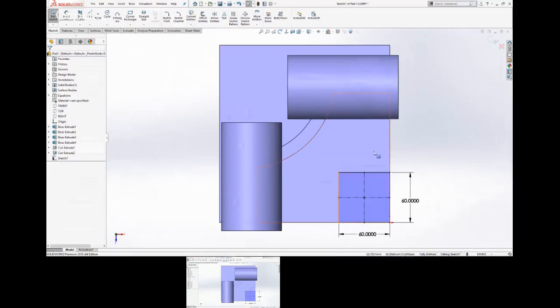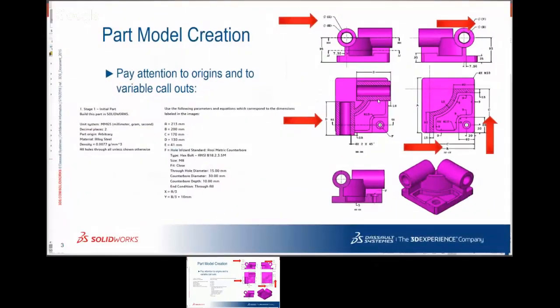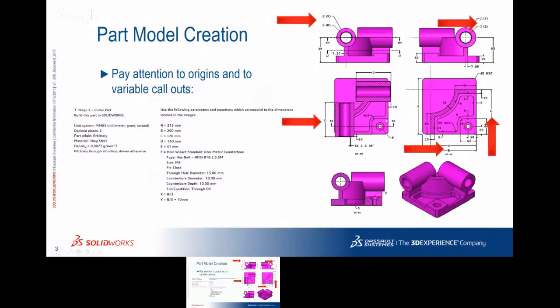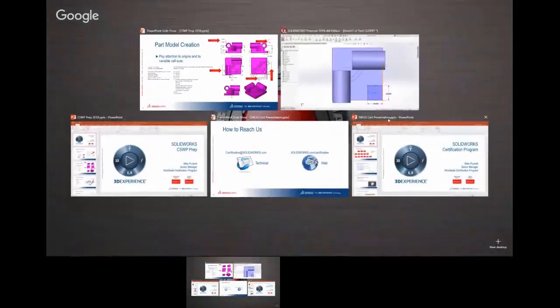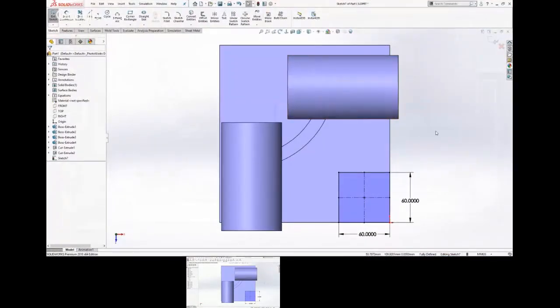So again, we have to put a fillet on that corner. Right here, it calls out a 15 millimeter fillet on the edge. I'm open for anybody's opinion on whether it should be at the sketch level or a feature level. In this case, the way it's dimensioned, I'm tempted to just put it at the sketch level because I'm not using a center rectangle, which sometimes can cause some errors because you trim away that corner, and the offset depends on it. Yes, that is true. So in that case, I think it's better to put it as a feature. But in this case, it works.